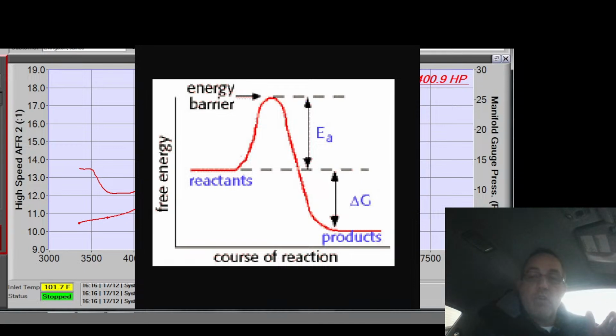That's important to know. So one way of doing that is with a teeny tiny gap. If you got a teeny tiny gap and you're in a super, super dense environment with stuff like water and steam or whatever you have in there, it's possible that even though you have enough energy to light off a few, you quench the whole combustion event out. It's not very easy to happen with just fuel. It's really easy to happen with water injection. But you can quench out your burn. It is possible.